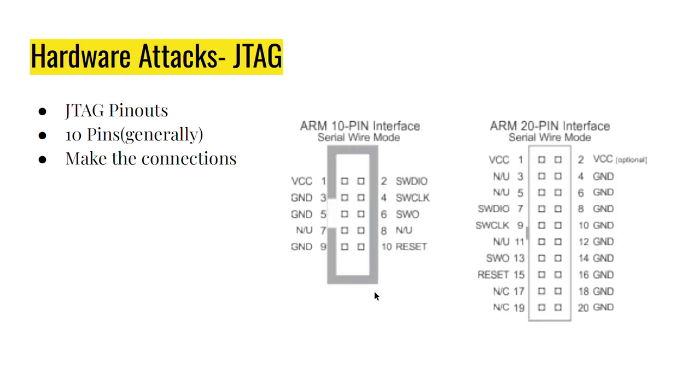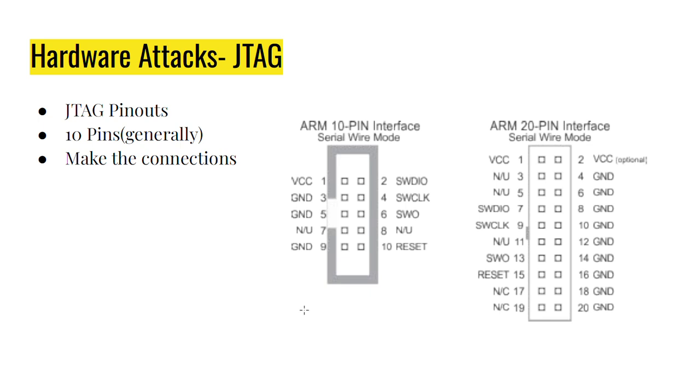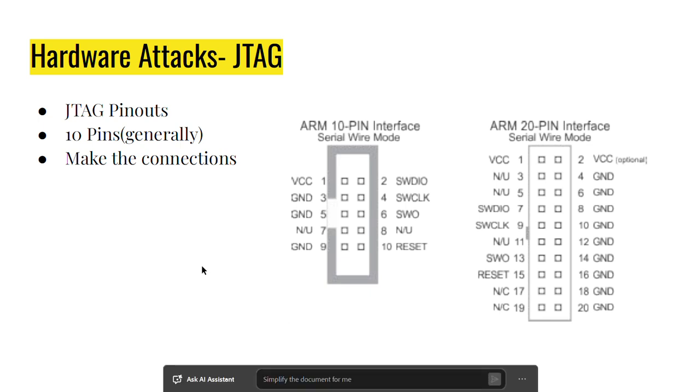So this is a type of hardware attack which includes JTAG pinouts, and there are different types of JTAGs. In some cases there are 10 pins generally. There are also places where there are 20 pins. So it all depends, and this is how you make the connections.